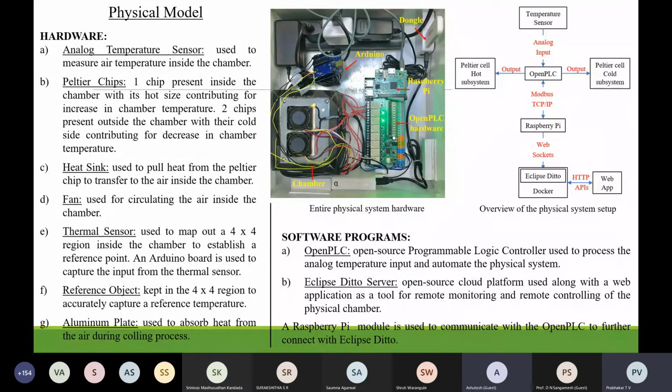You can definitely use Matlab Simulink software for creating your PID loops. Now, how do you translate the PID loop that you created in Matlab onto your target system? It might have to create a C code or something, and that C code is what you will fuse onto your controller, isn't it? Physical microcontroller.